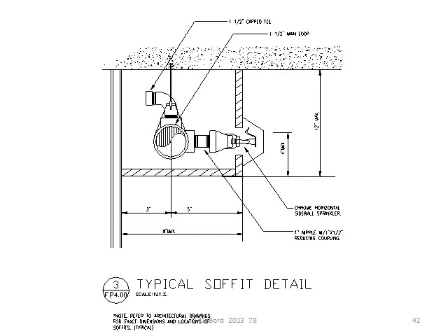This is a typical soffit detail that we made for an existing building that was not sprinklered. We were running a sprinkler pipe in the corner of the corridor, and they wanted them to be concealed, so they built a soffit, and there are certain limitations to the size of the soffit, but it's very hard to get all this stuff in there. We wanted to have a sprinkler loop, a sidewall sprinkler that's concealed, and we wanted to have the ability to tap into that to run sprinklers into other rooms later. Right now, it was only partially sprinklered.